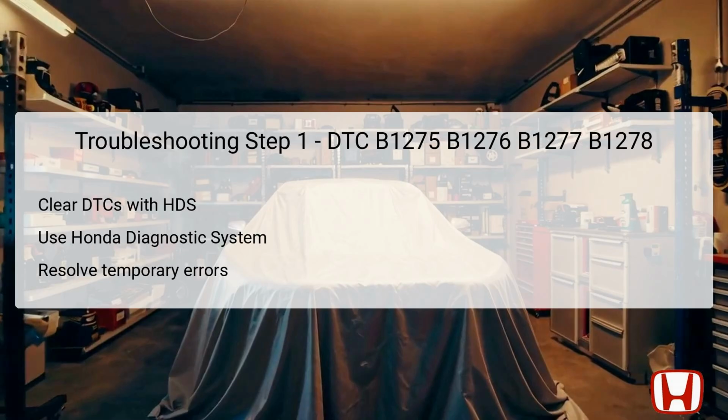The first step in troubleshooting DTC's B1275 to B1278 is to clear the existing diagnostic trouble codes using the Honda Diagnostic System, HDS. The HDS is a specialized tool designed for Honda vehicles, allowing technicians to interface directly with the vehicle's onboard diagnostics.